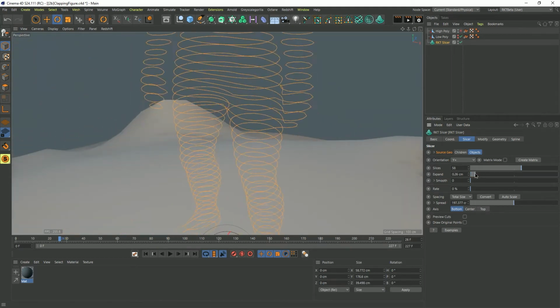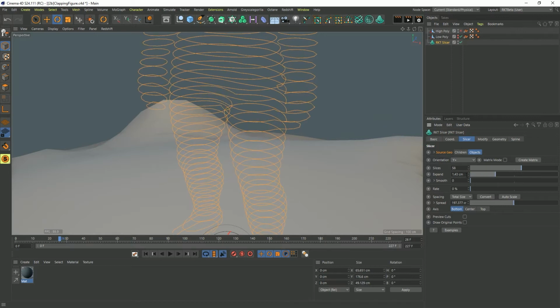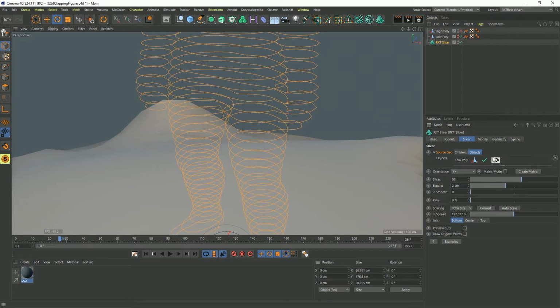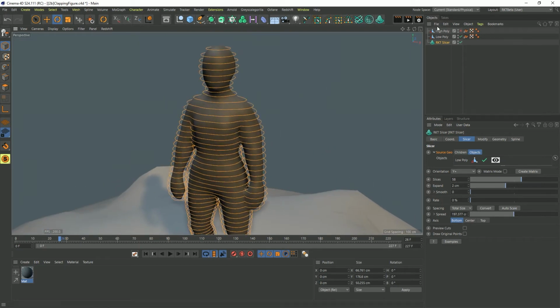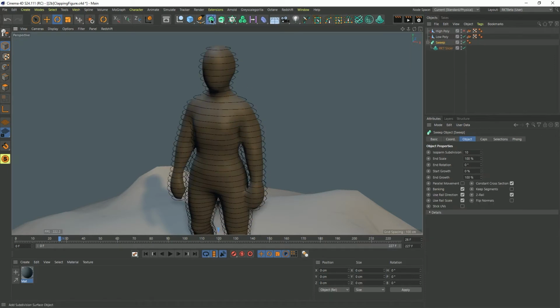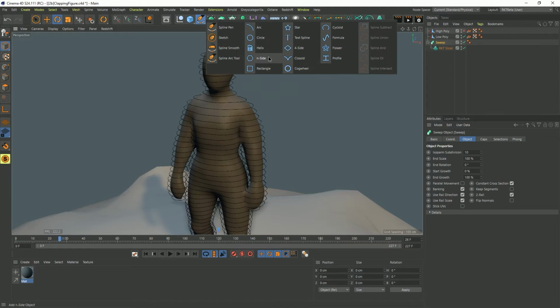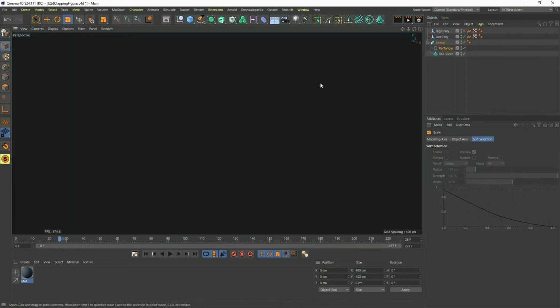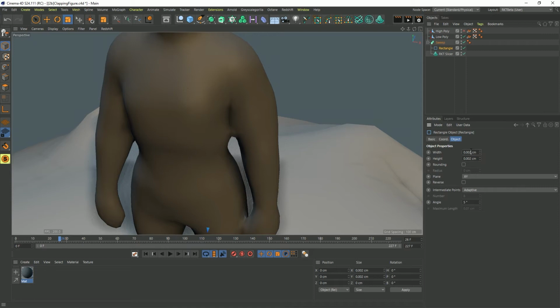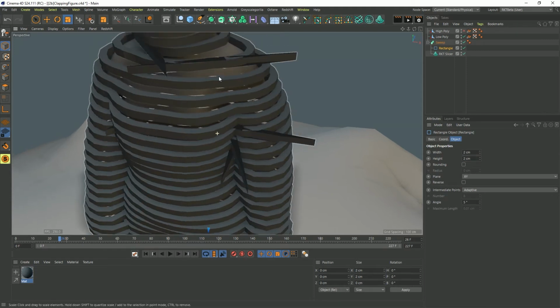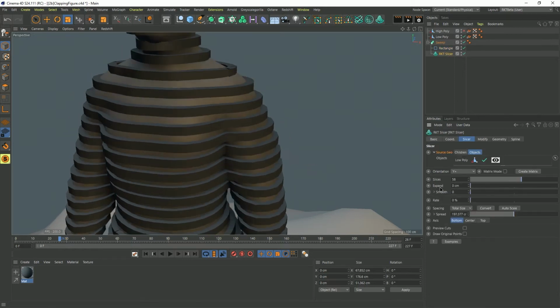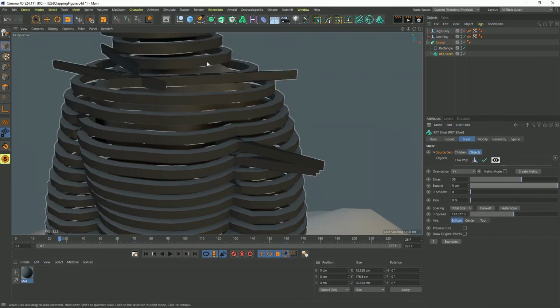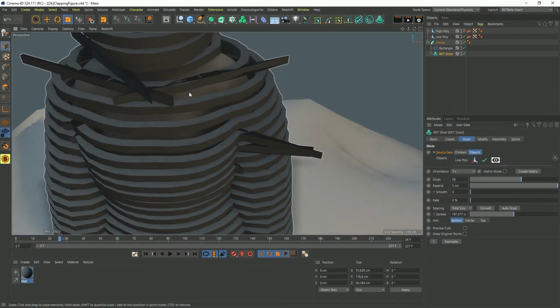As a quick for instance, just for fun, how about we expand this out, let's say exactly 2. I'll unhide the object, so we'll bring that back in again. You can kind of see we get this nice outline of it traveling around. And if we were to sweep this, because of course it's a spline, feed that into a sweep. Into the sweep, I shall feed a rectangle spline, which will be huge, but true to scale. Whoop, set those to 2 by 2 just to see them. And now you can see that's expanded outside the character, and we could push that in or out. Let me show you that. We can push this in, which is the original, or push it out. But now you can see that the sweep is getting upset about some of these crisscrossing lines.